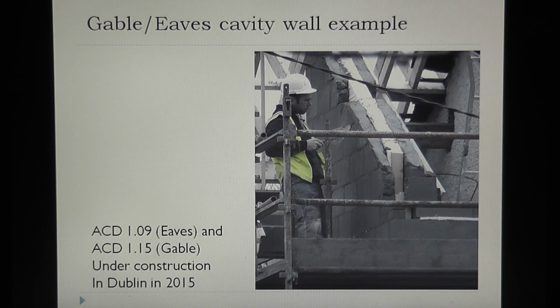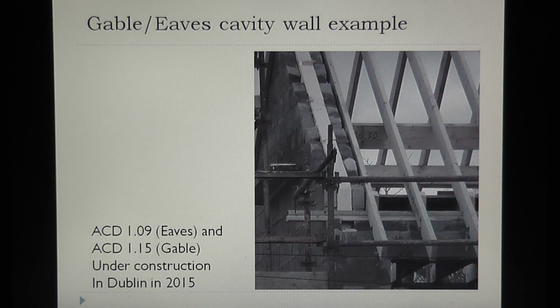You can see it's very standard construction. It's a 100mm cavity block wall with a full fill cavity insulation. In this case, it's a phenolic foam, and that's the completed detail before the roof was applied. So you can see a very standard cavity wall, both the wall at the front and the gable wall, and in this case the gable wall is fully insulated all the way up to the eaves because the room inside is going to be converted for use at some point. Cut timber roof,